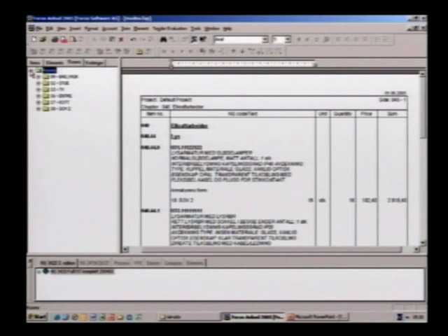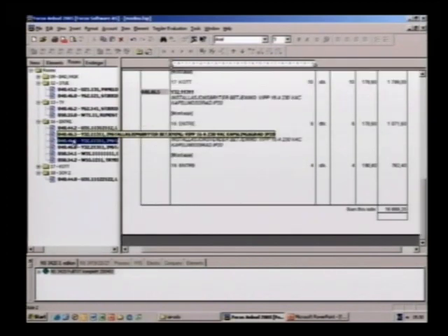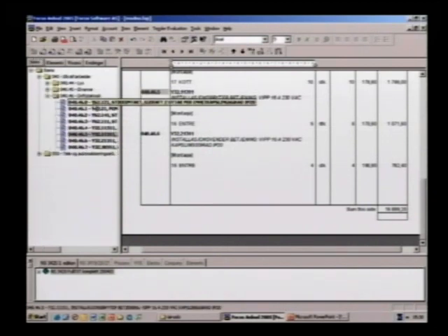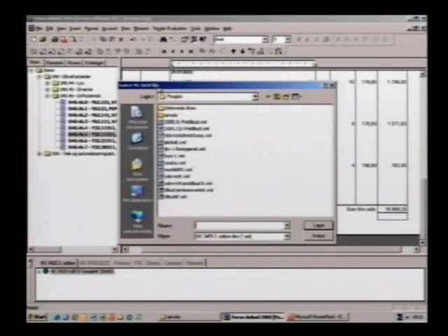Okay, can you stop for just a moment? Because I don't know if you got this. He was just importing an IFC file. And not only do we have that this is light fixtures of this and this type, but it also says which space it's located in. Because, of course, it's combined these two building models. One from the architect with the space naming and everything, and then he places these electrical components, and of course it's allocated to that space. So we'll see the number and which space they are in, and he can sort this in all kinds of ways. So, sorry, but just continue.